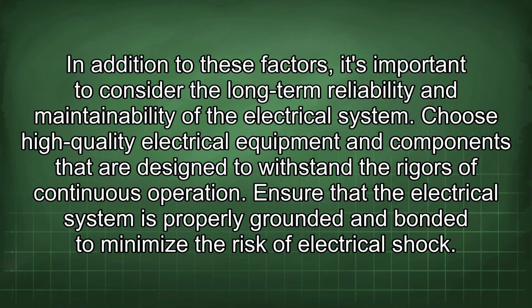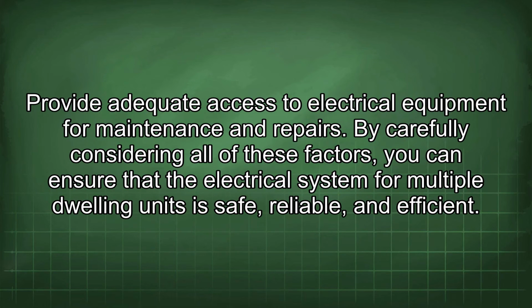In addition to these factors, it's important to consider the long-term reliability and maintainability of the electrical system. Choose high-quality electrical equipment and components that are designed to withstand the rigors of continuous operation. Ensure that the electrical system is properly grounded and bonded to minimize the risk of electrical shock. Provide adequate access to electrical equipment for maintenance and repairs.